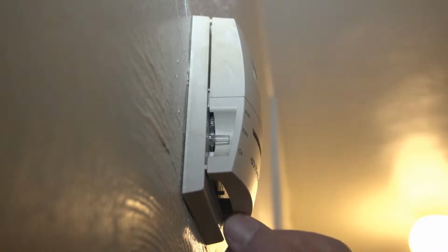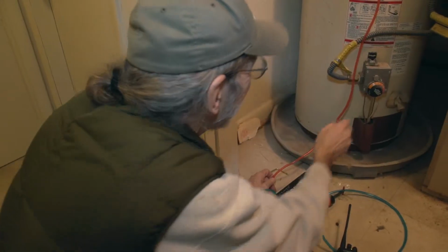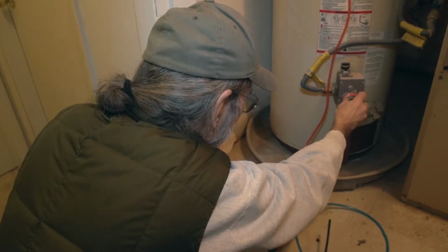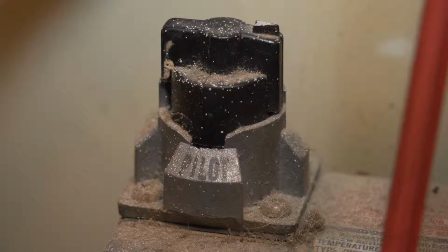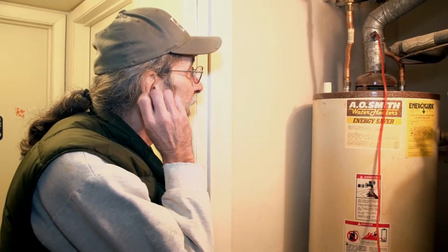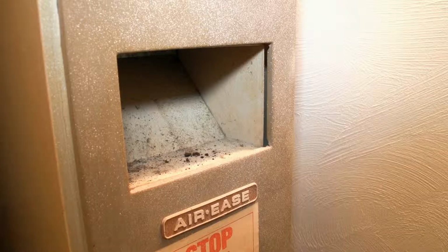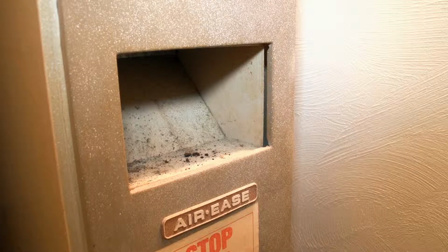Now we're going to go ahead and start our CAS test by turning off any combustion appliance in the house. We do not want any of these appliances to fire or start up in the middle of our setup, as this could affect both our health and the safety of the occupants. We'll go ahead and turn off or turn to pilot any water heaters, furnaces, stoves, ovens, or any other source of combustion gas in the house.